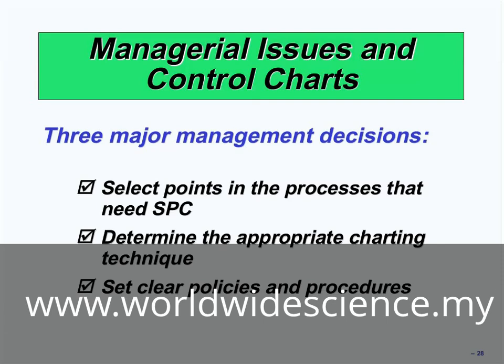If you want to work based on number of defective, you should select P chart or C chart. And if you want to measure one variable such as temperature, weight, and something like this, you should select X bar chart or R chart to monitor the process. And after monitoring the process and analyzing data, you should set clear policies and procedures, for example, to solve problems and something like this.